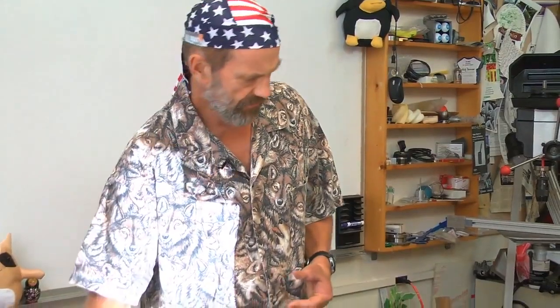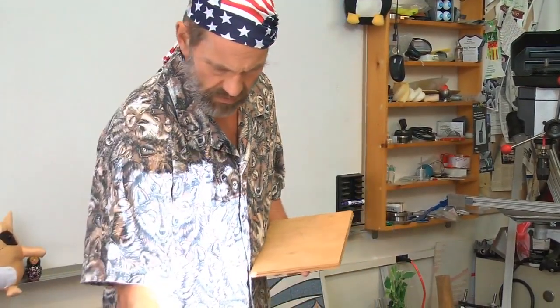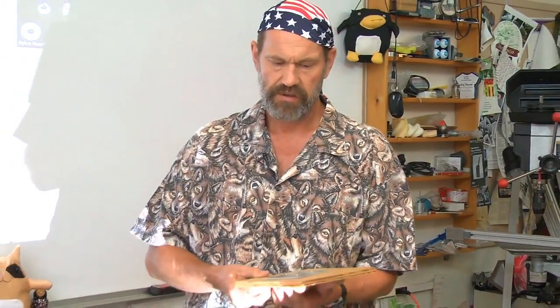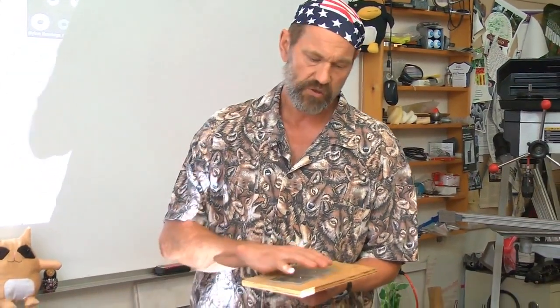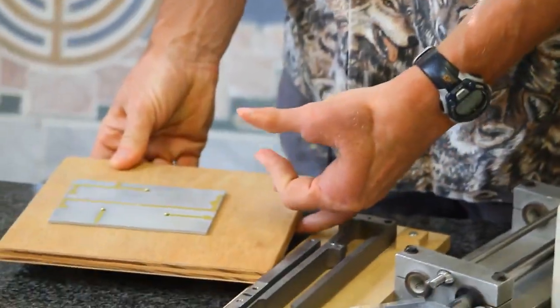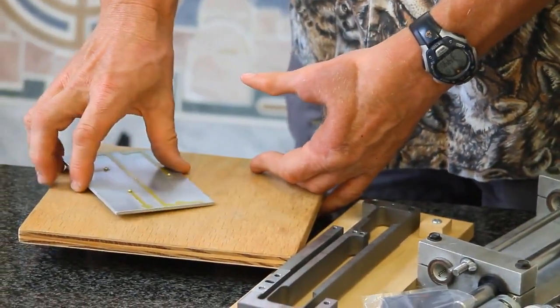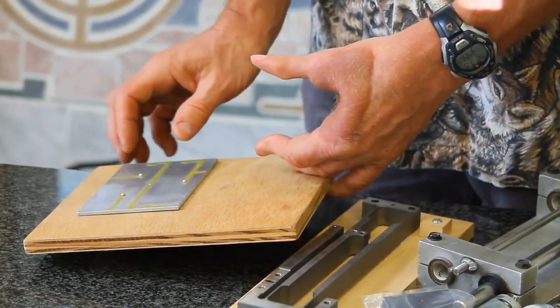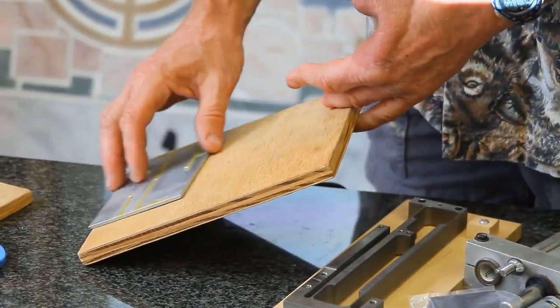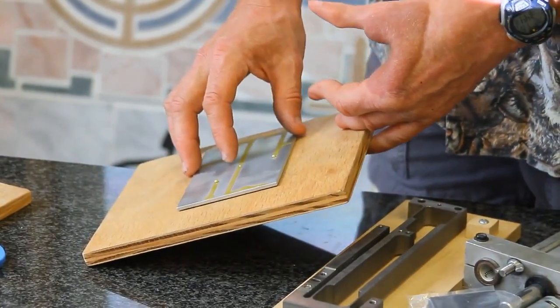If I have metal on wood, how do I know what the coefficient of friction is? You can go online and say, what is the coefficient of friction of metal on wood? Well, it depends what kind of metal, what kind of wood, what the surface preparation is. Is it greased or not? And remember, you can evaluate the coefficient of friction just by looking at the tilt. The tangent of the angle equals the coefficient of friction.